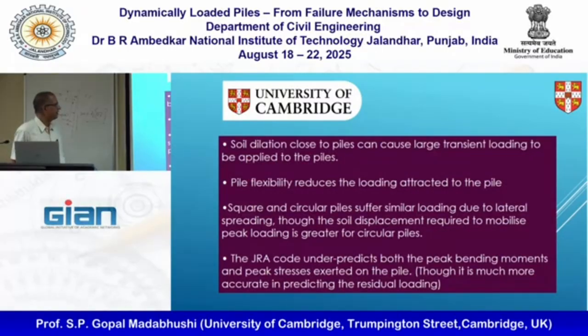So, in summary of single pile, what have we learned? We are very sure that soil dilation close to the pile causes this transient loading. That's why you're getting those suctions and differential earth pressure, pore pressures.